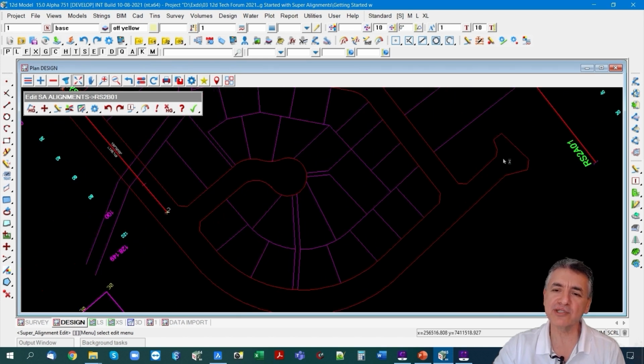What I'm going to do is draw 2 lines here just across the road reserve, 2 perpendicular lines to the boundaries there, and we're going to use that as another snaps CAD to show you that option. I'm going to go on the side menu here under the CAD line option and pick on that, and it's going to draw it on the base model because that's in the control bar at the top there.